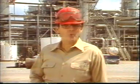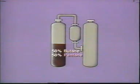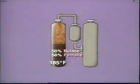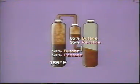One way to visualize what happens inside a distillation column is to follow the separation of a liquid mixture through a series of stills. Suppose our mixture is composed of 50% butane and 50% pentane, and we want to obtain a pure butane product. Butane boils at a lower temperature than pentane, so if we heat the mixture to, say, 185 degrees Fahrenheit, more butane will be vaporized, and the condensed vapors will form a liquid that's enriched in the light component, butane. We can further purify this liquid by placing it in a second still and heating it at a slightly lower temperature.